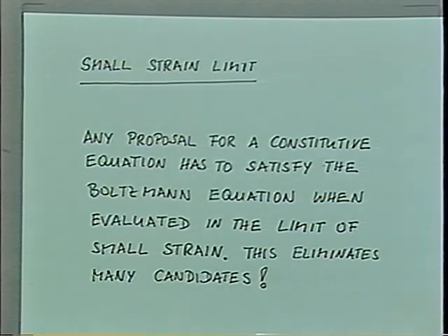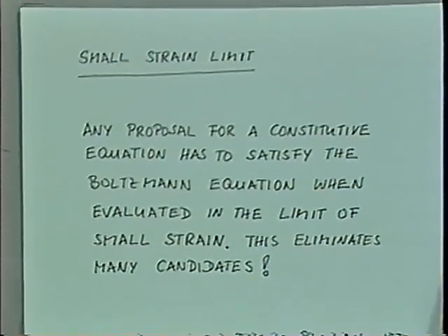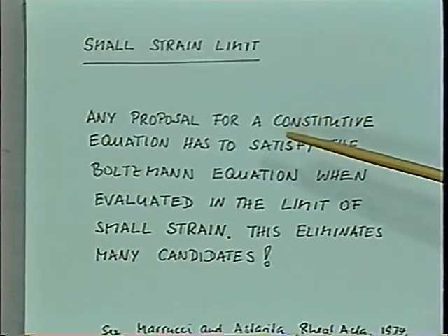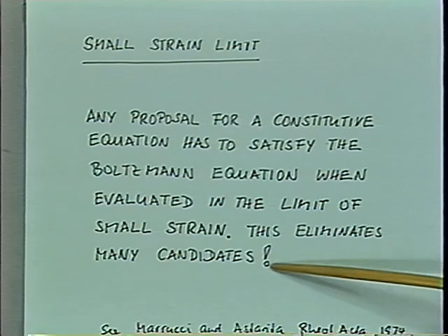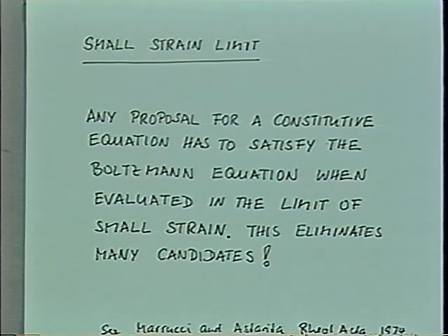We want to build on that information. Therefore, the experiments tell us that at smaller and smaller strains, any constitutive equation, if it describes the experimental behavior, should reduce to the linear viscoelastic limit, and that eliminates many, many constitutive equations.